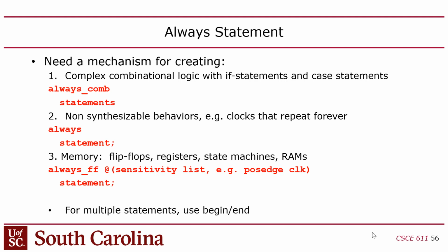So how do you fix this? Easy. You just put a default value for C right above that if statement. Then C may get changed twice, may be set twice, but only the last one will take effect, will matter. So that's basically always statements for combinational logic.